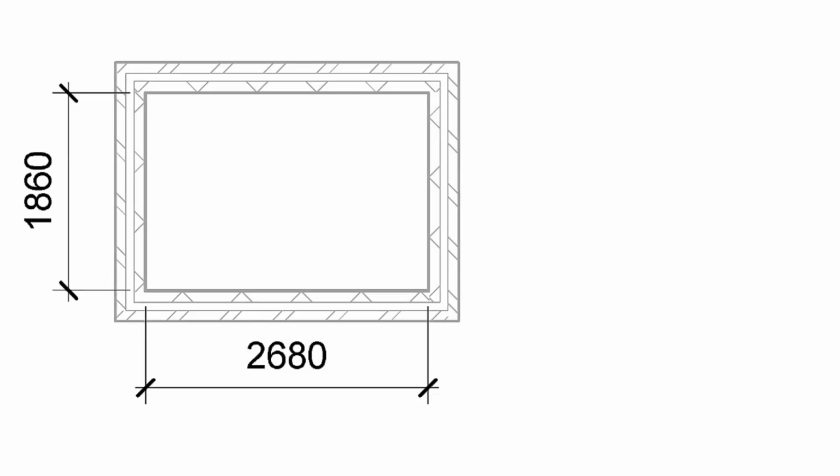Once we have the centre lines, we can multiply by the heights and obtain the areas of these skins. And this is how they are priced, by their square metre area. Let's have a look at this plan view. It's enlarged to make it easy to follow, made up with a composite wall and with internal dimensions of 2.680 metres by 1.860 metres. The internal girth, or the distance all the way around the interior, is therefore 2 by 2.680 plus 2 by 1.860, which gives us an inner girth of 9.080 metres.